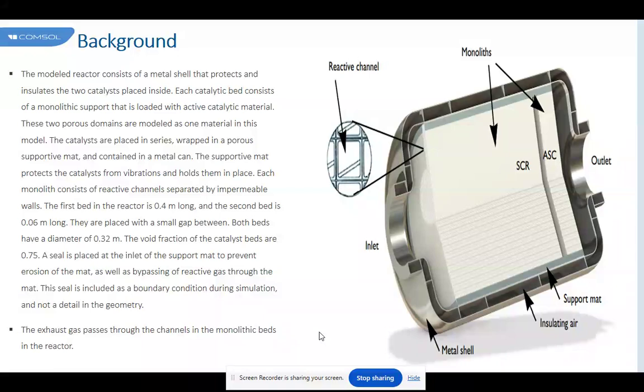Conclusion and discussion. As stated in the introduction, the main goal of this work was to investigate the effect of the substrate material on the steady state and dynamic behavior of the catalyst monoliths. If the objective is to operate the monoliths in the region of multiple steady states and on the ignited branch, then we have shown that monoliths with high conductivity substrates, metallic and or high aspect ratio diameter to length, lead to the ignited branch at lower inlet gas temperature, typically between 60 to 100 degrees centigrade.